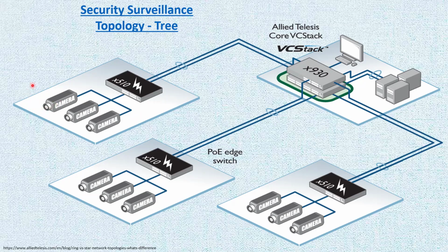So you gotta make sure that this is actually 48 volts DC on certain pins, and not 24 volts, for example. And also, you need to make sure that the power on the PoE overall for the switch can handle the power that each camera and all of them combined are going to drain from that. So when you're buying that, you need to consider these things.